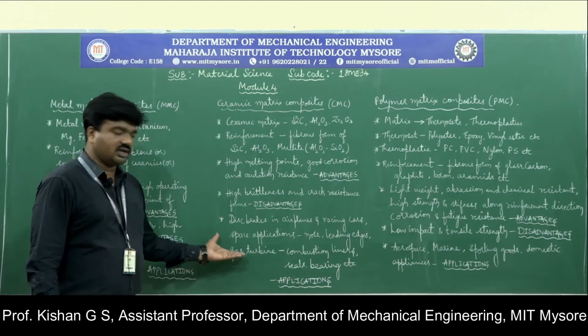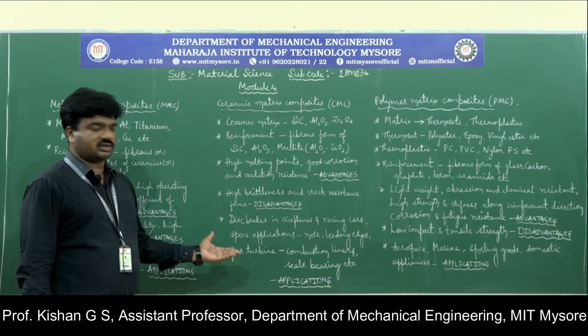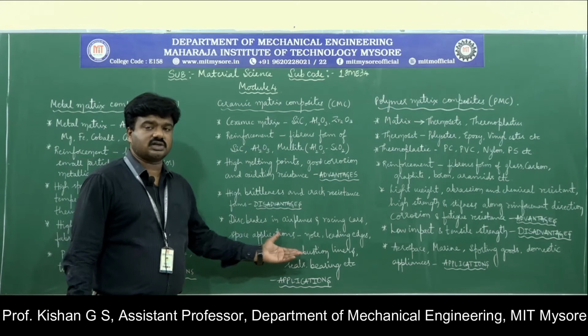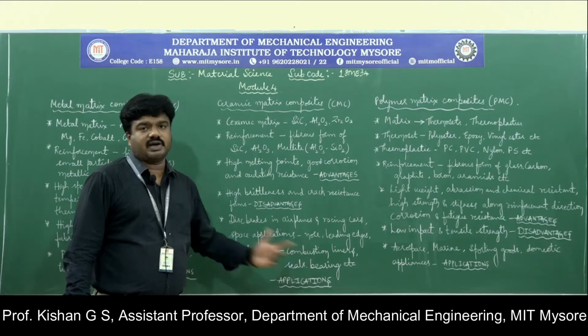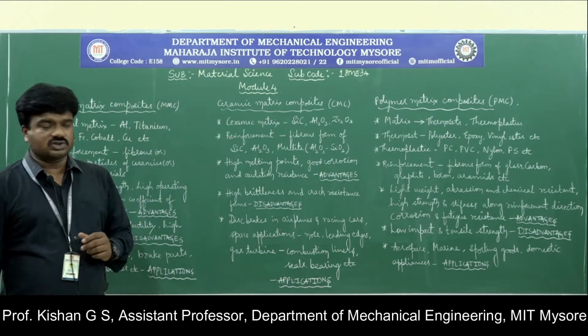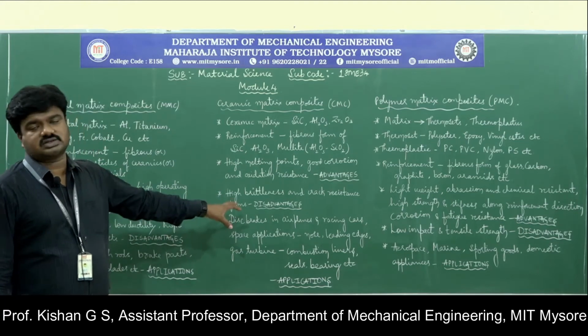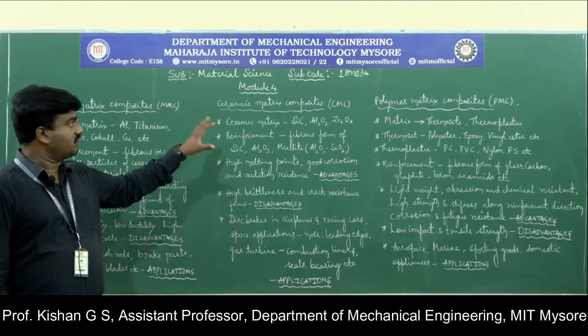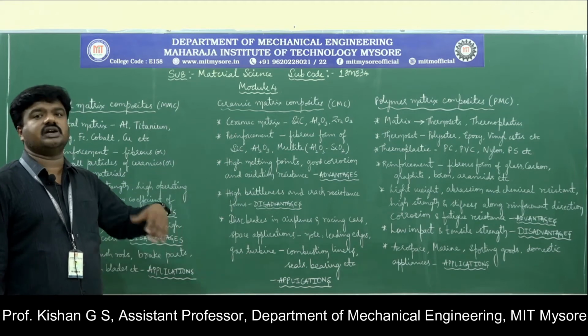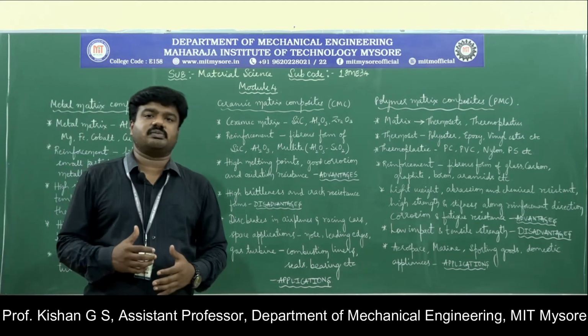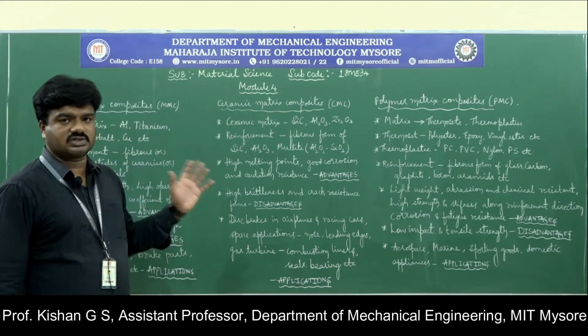Moving on with the gas turbines, its use is considered in the combustion liners, in sealing devices as well as bearing units in the gas turbine. So these are a few of the listed applications for ceramic matrix composite. It is basically due to the less wear parameter that is seen here in the case of ceramic.